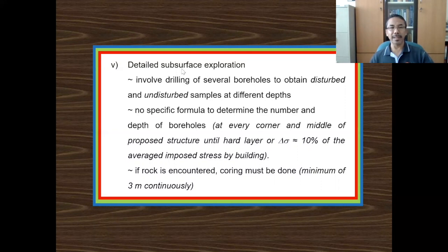With regard to this detailed subsurface exploration, there's no specific formula to determine the number and depth of boreholes. There's no formula, no rules. Normally, it's based on our engineering judgment. Based on our engineering judgment, normally this detailed subsurface exploration is performed at every corner and middle of the proposed structure. Those are the locations.